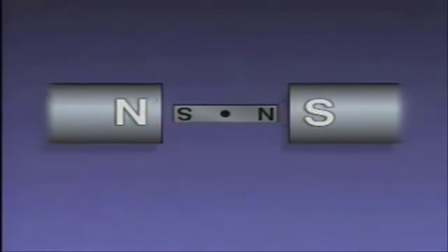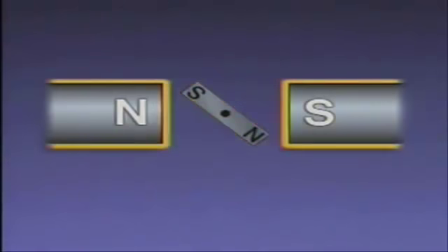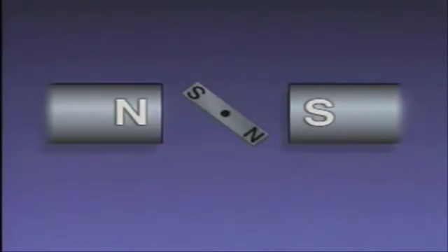At this point, the bar magnet would stop unless it had enough momentum to carry it past the poles of the permanent magnets. To keep the bar magnet rotating, the polarity of either the bar magnet or the two permanent magnets must be changed. In a DC motor, what is changed is the polarity of the armature, which is represented by the bar magnet in this example.